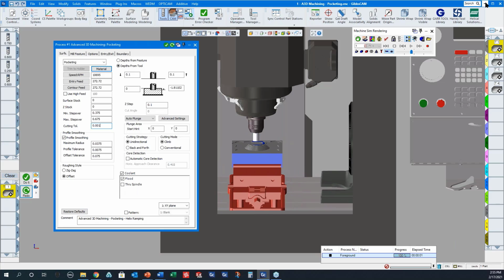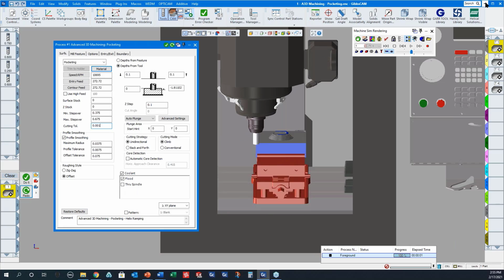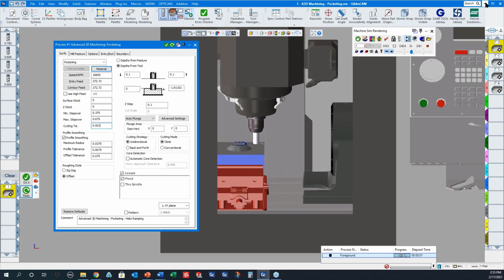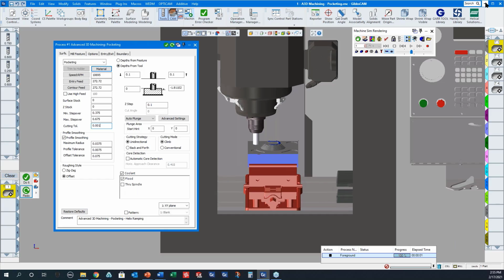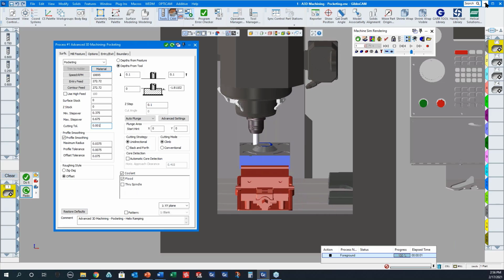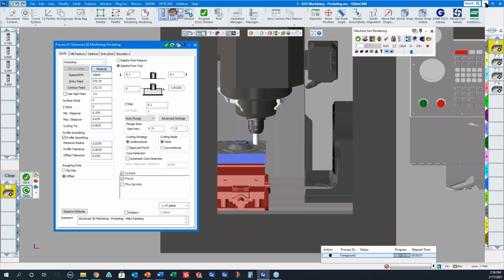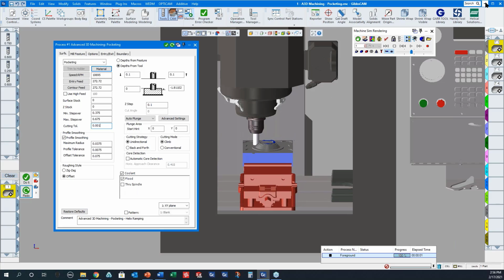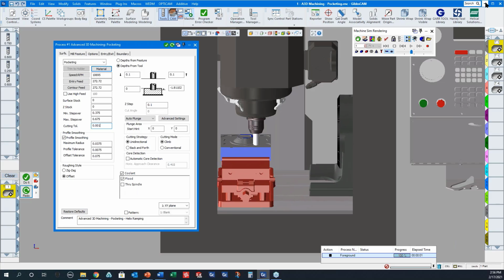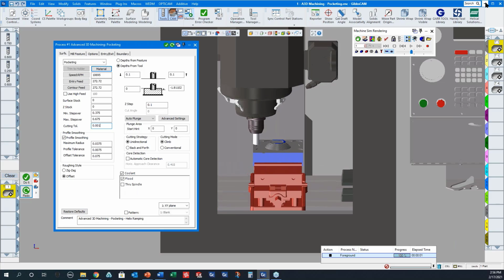If you're specifically talking about Haas machines or Fanuc controls for that matter, I would point out that on the Haas machine, there's a G187 code, either G187 P1, P2, or P3, that controls the smoothness of the toolpath and how fast it runs on the machine.